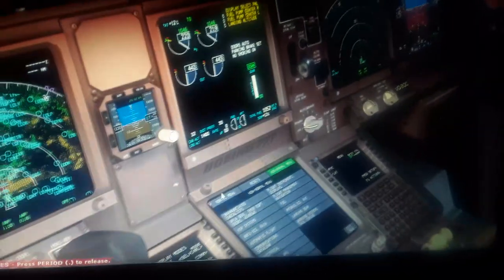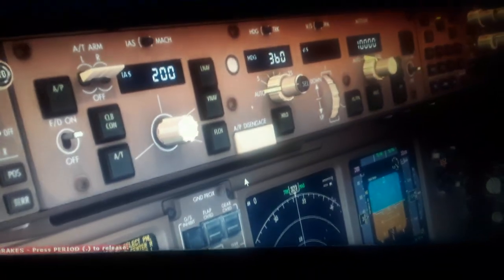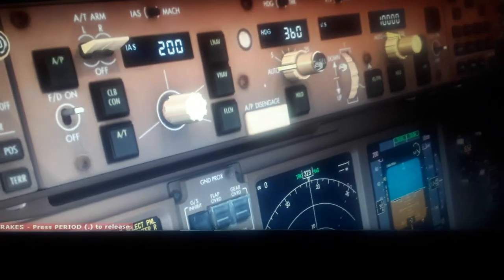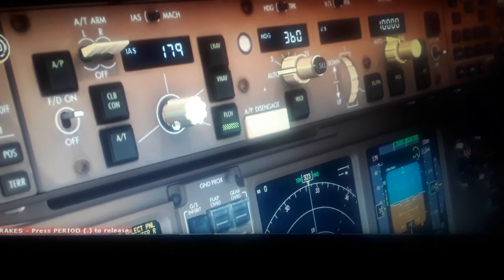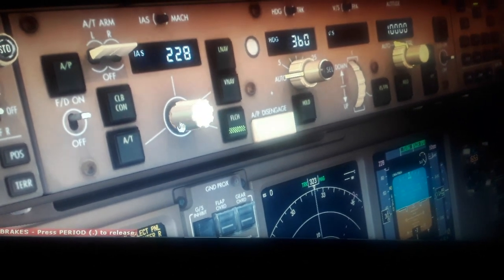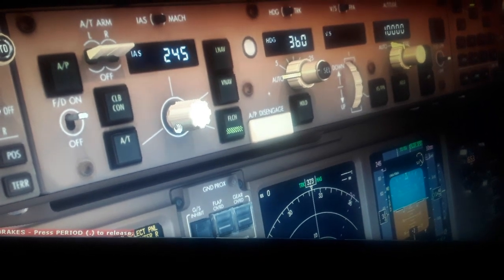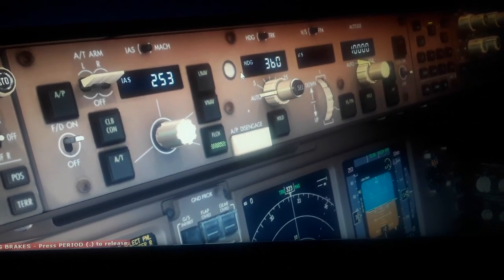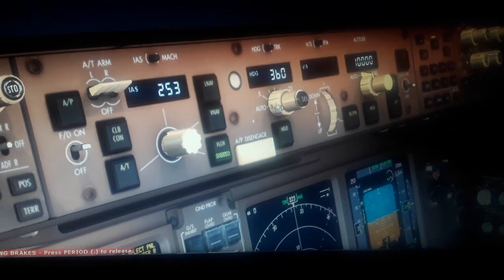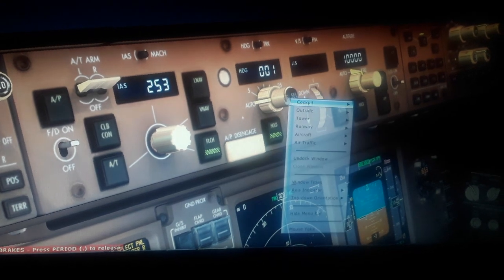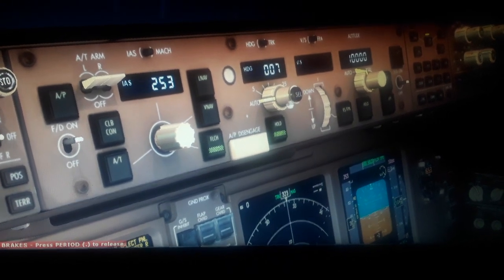We can also set here the flight director on and off, and on the other side we can set the flight level change like this. Select an indicated airspeed or Mach, like 253 for after takeoff. This is also depressible. We have the LNAV, the VNAV, the climb continues, the autothrottle, the bank angle limit for the flight level. Also you can deselect this, you depress this switch.